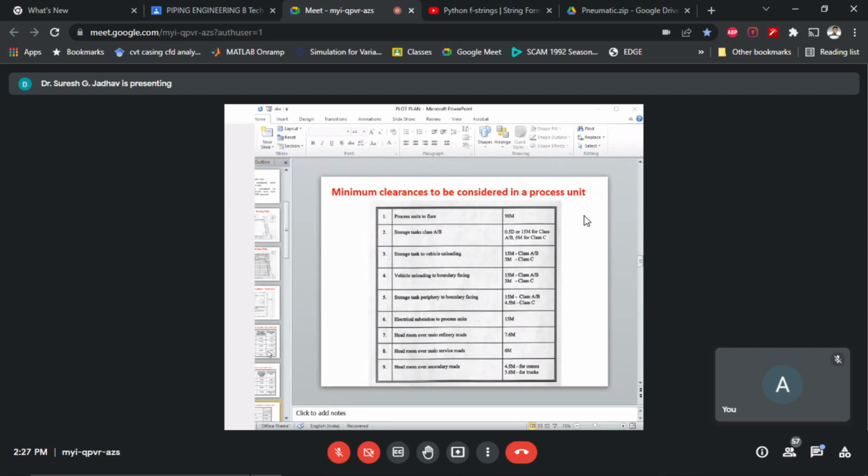The storage of LPG, that is liquid petroleum gas, can be placed underground or covered by earth in such a manner and subject to such conditions as may be specified by the notification by the central government. And above ground vessels for storage of corrosive, flammable, or toxic gas in liquefied state shall be provided with an enclosure wall around the ground. The minimum distance between the vessel and enclosure wall shall be the diameter of the vessel or 5 meters, whichever is less.